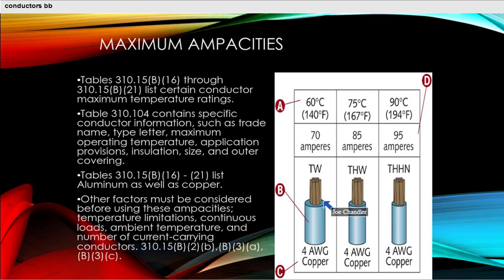So whenever we look at ampacity, you see the rating associated with the temperature, and we'll see these values here, 60, 75, and 90, in Table 310.15(B)(16). This is your most common table that you'll use. You notice there's more. They go all the way through 310.15(B)(21), but the one you use most often is right here, 310.15(B)(16). Now, here's another table that is used occasionally, and it's moved to the very back of Article 310. It used to be up at the front, before these tables, but now it's buried way back in the back.